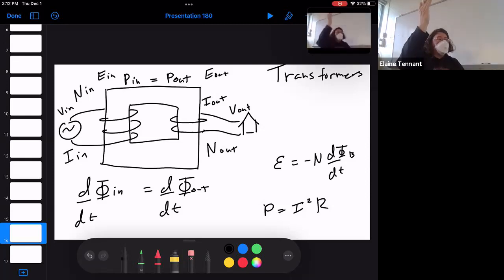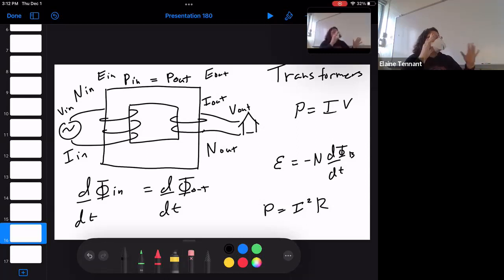Okay, so if you want to transport electrical energy, you want to do it at a low current and therefore a high voltage. So you can't fix power. Energy is conserved. We can't change that. But what we can do is say, let's dump our current really low, ramp our voltage very high, and then just try to transport this potential difference.